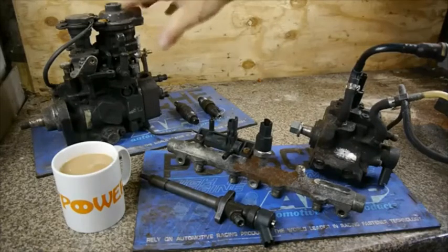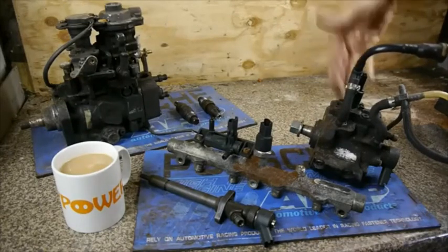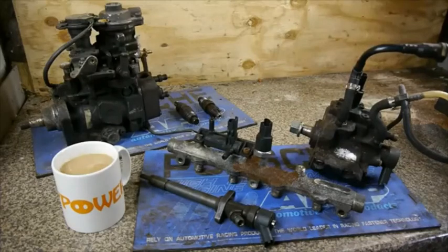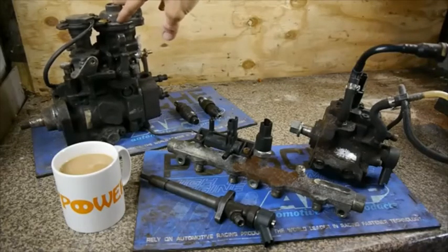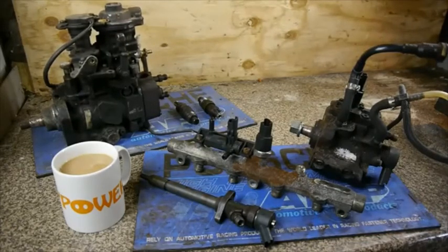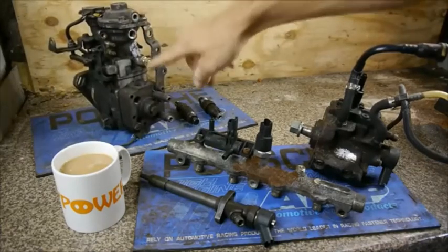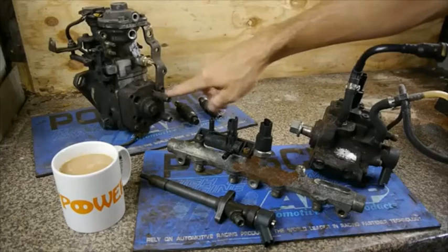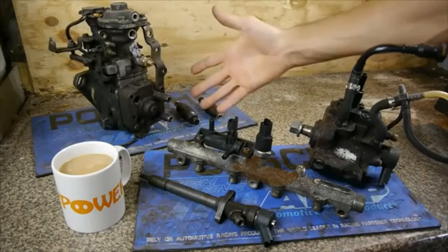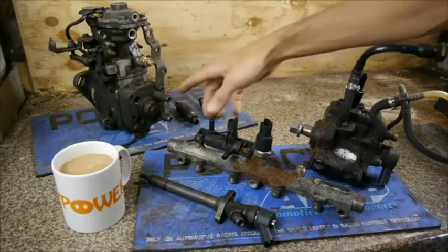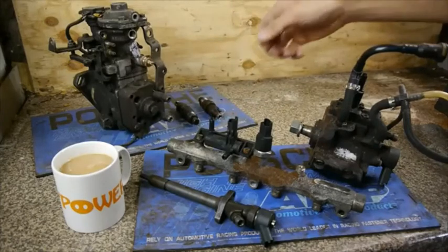The second main difference between these two fuel pumps is this one just simply creates a pressure. It doesn't actually determine when each injector fires. However, this fuel pump, an early Bosch fuel pump that runs on XUDs, etc., also determines the point at which each injector fires by the delivery valves that are on the end. On the end of the injection pump, there are 4 delivery valves on this one, so it's a 4-cylinder engine. Some are 6, and that would obviously be a 6-cylinder engine.